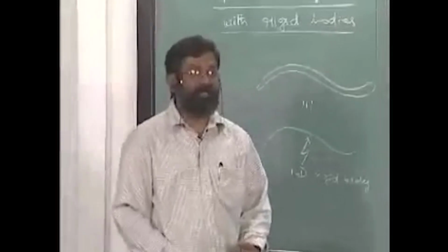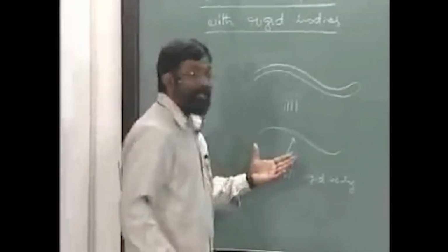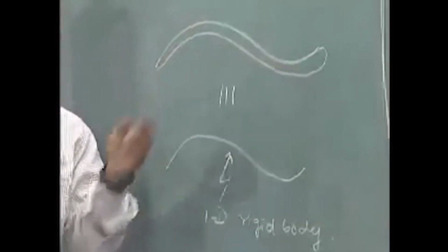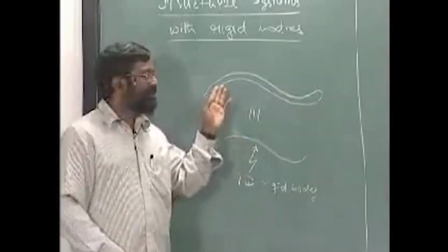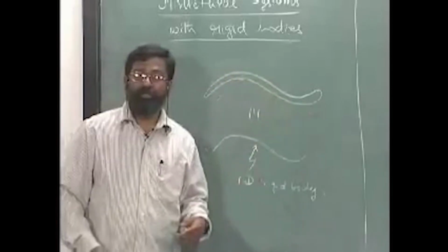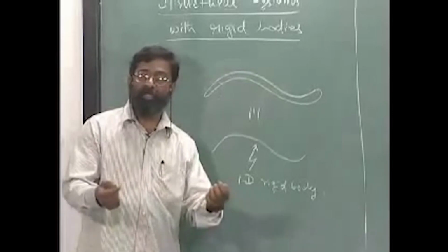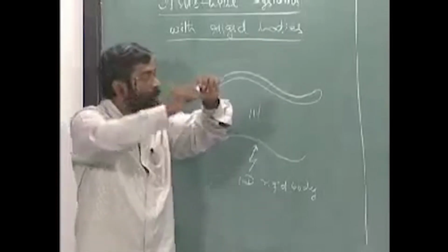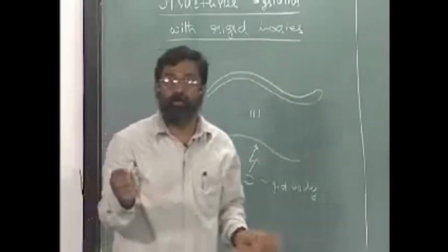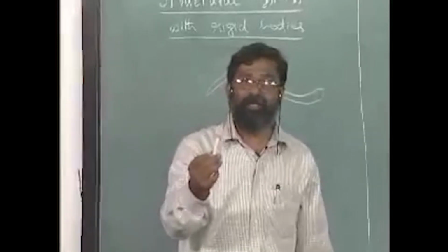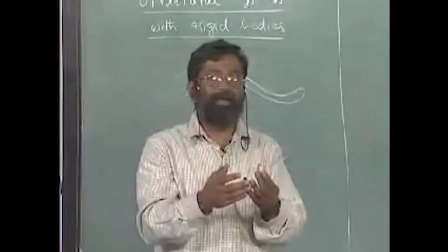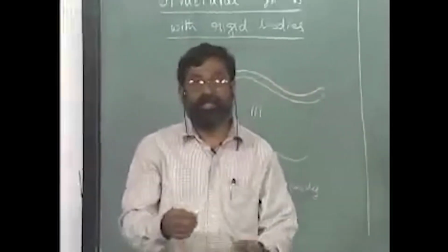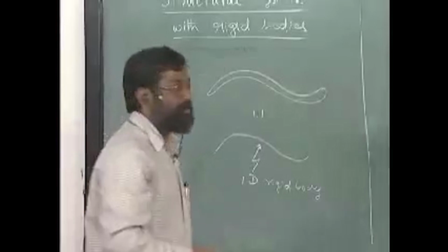We will look at some of the examples at a later stage, but let us examine how we analyze for forces within this rigid body. The reason why you would want an analysis of the forces within the rigid body is to understand whether the body can take the load or not. For example, if I am pressing this body hard on the board, how hard can I go before this breaks? If I know the internal forces, that will give me an idea of whether it will break or not for the particular situation that I am talking about. So such an analysis is called analysis of internal forces in structural systems.